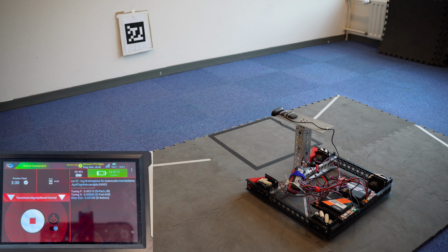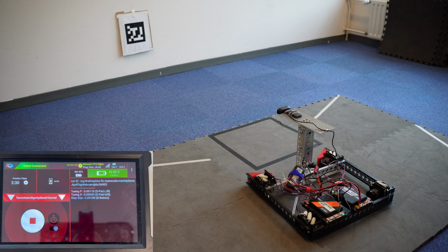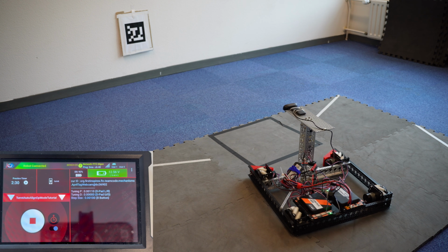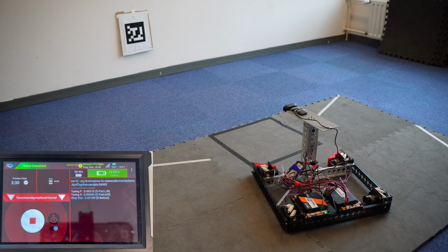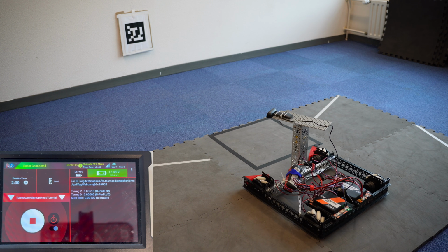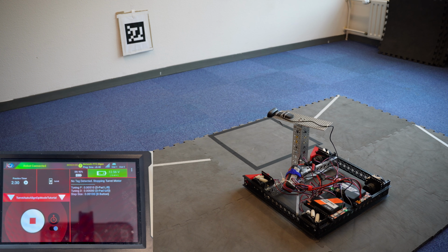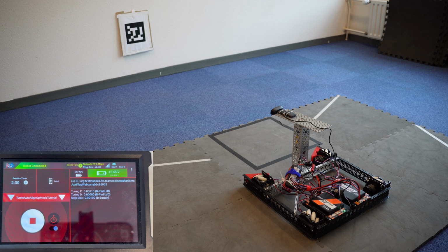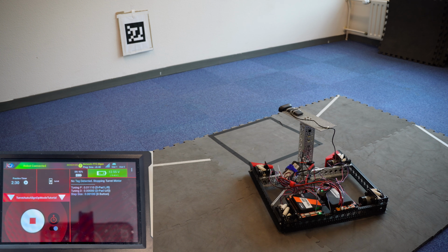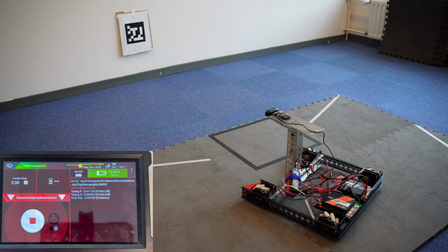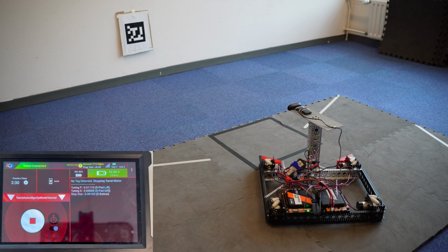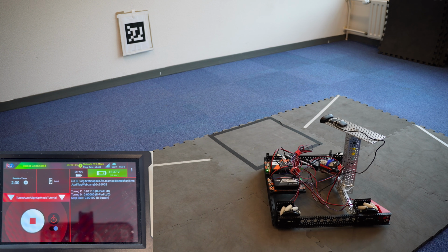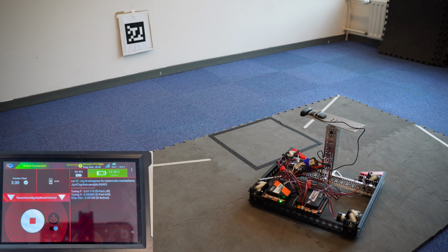So if I use left and right, I can start increasing my P, and we can start seeing that as I rotate, it wants to kick a little bit, but it doesn't have quite enough P value. So I'm going to increase that P a little bit more until we actually start rotating towards our target. And that is starting to be more on the path of what we're looking for, but our P is still a little bit low at 0.05. So let's go up to something like 0.1 and see what that looks like. That looks more along the lines of what we would expect for a P value to be auto adjusting. Let's go ahead and flip ourselves back.